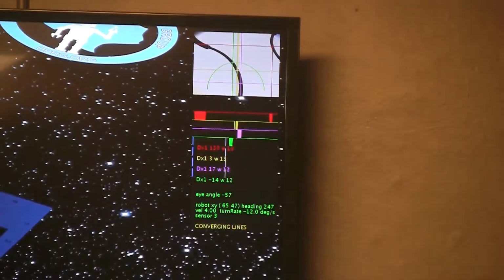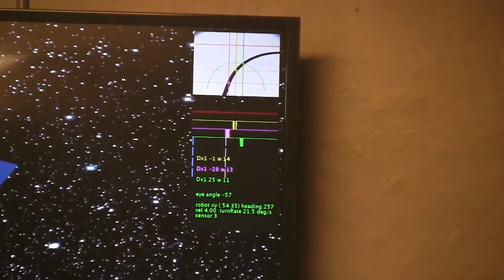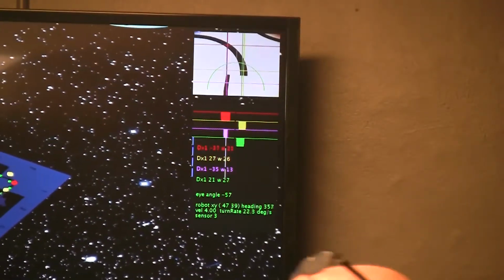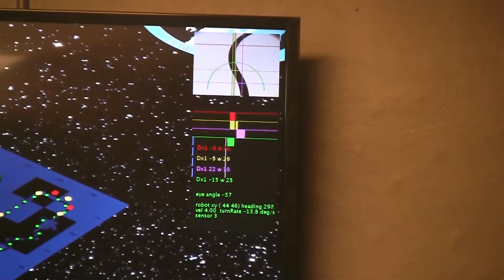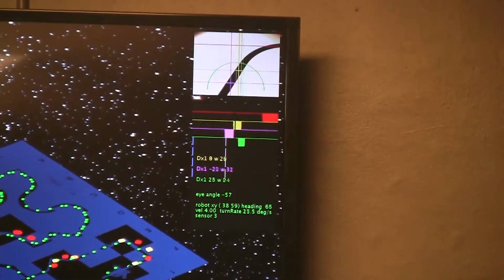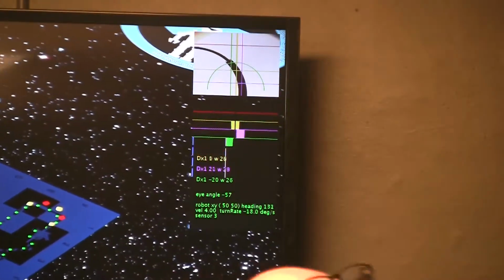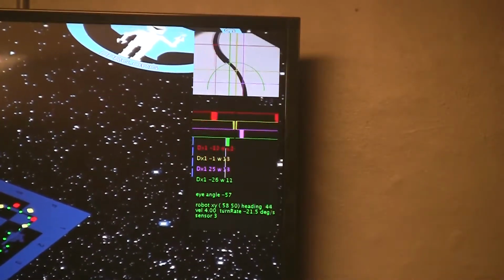In other words, if I see something, that chair right there, and I say, okay, it's 8 feet in front of me, my odometry has to be reasonable as I approach. I say I've gone 6, 7, 8, okay, good. So it's where I expect it to be. But yeah, the green crumbs are nothing, they're just visual for us to see how well it's tracking.